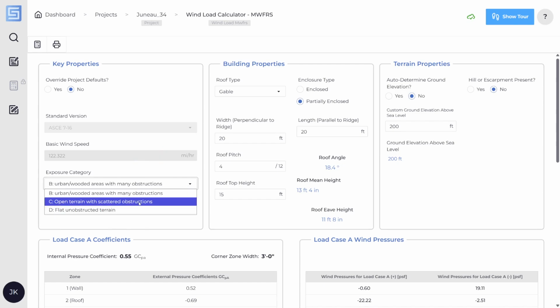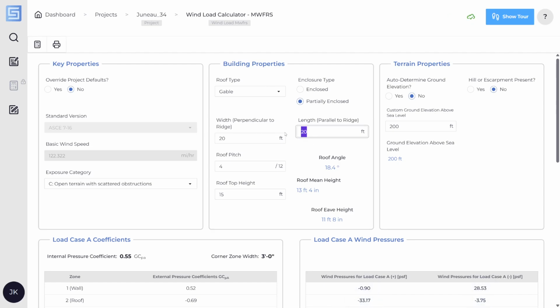We're actually going to be, C here is a gable roof. It is 70 foot long, 40 foot wide, 6 in 12. Top of roof, I think, was at 28 feet. Gives us 23 mean roof height. That's correct.